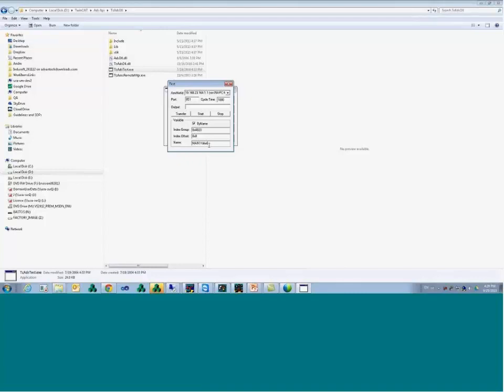In that case, I have to put a valid variable name. So I have my gvl.testvar. I'm going to start the communication. All right, it works. So if this guy works, the driver is going to work as well. If by any chance I had this wrong, the variable name here, I'm going to put, for instance, main.testvar that I was trying. I'm going to start. See, it fails. If it fails here, it's going to fail on Web Studio.